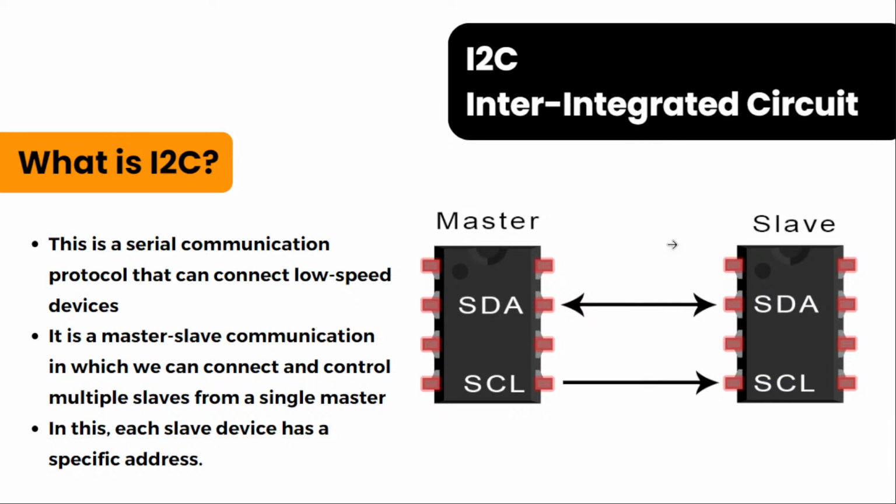Before getting into this, let me give an introduction about what is I2C. I2C combines the best features of SPI and UART. With I2C you can connect multiple slaves to a single master like SPI, and also you can have multiple masters controlling single or multiple slaves. This is really useful when you want to have more than one microcontroller logging data to a single memory card or displaying text to a single LCD.